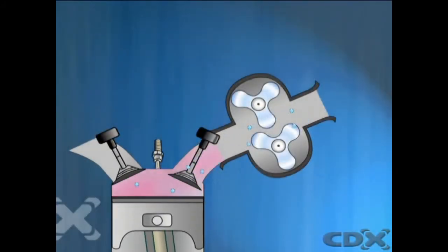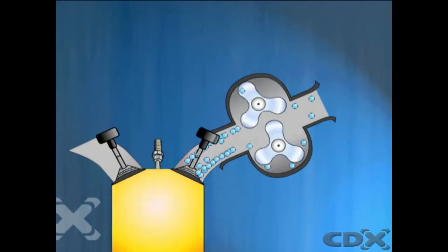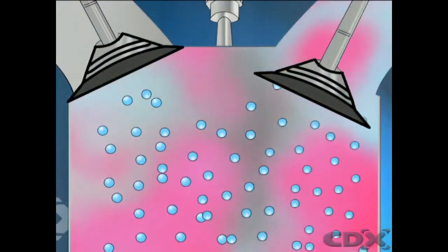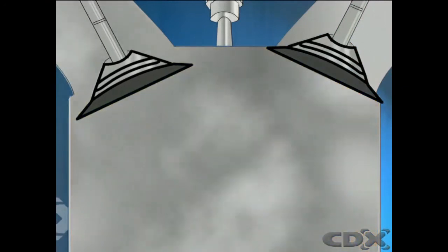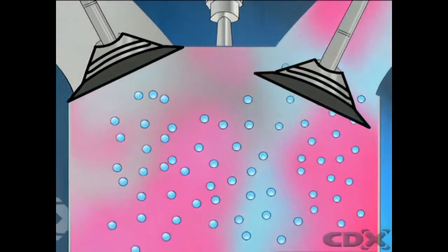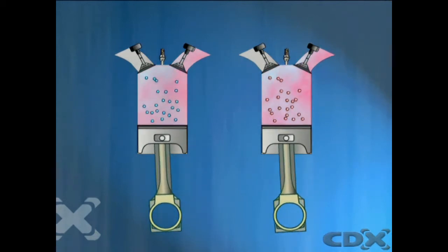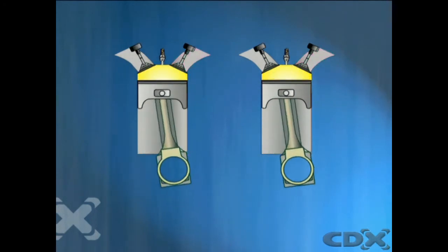A turbocharger or supercharger is used to increase the volume of air in the engine cylinder by compressing the air above atmospheric pressure. More air in a cylinder means more oxygen molecules available for combustion, which means more fuel can be completely burned, giving greater power output. However, when air is compressed, it heats up, which causes the volume of the gas to increase, and that lowers the air density. Hot air under pressure in a cylinder contains fewer oxygen molecules than cooler air at the same pressure in the same volume.